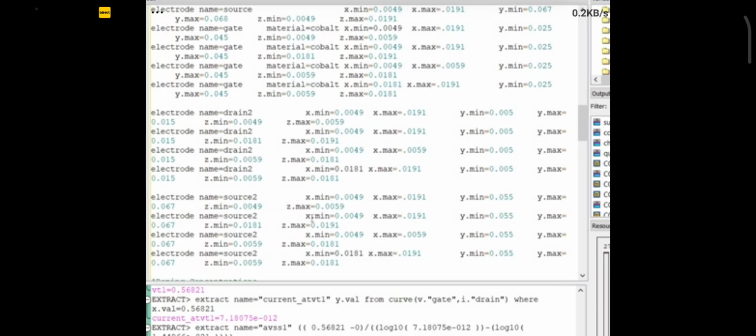If you want to run the program as it is, please note down all the positional parameters very carefully. If you make a mistake, you will get a runtime error. Most of the students are calling me and saying that they are not getting the result. If you do not note down properly, you will definitely get an error message. Please note down all the region material, electrode material with their positional parameters very carefully to obtain the same result.